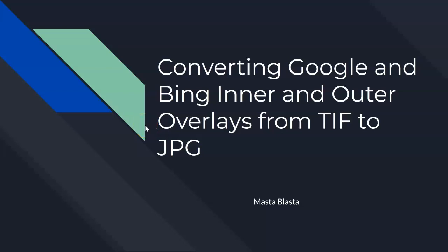So now what we're going to do is take those satellite overlays that we created from Google and Bing inside of QGIS, and we made them into those TIFF files. Remember, they're huge. They're like 1 gig each. Well, we need to compress those a little bit, and we're going to make them into JPEGs, which is a picture format that we can use inside of Unity, and we can also use that inside of Inkscape to create our splines.